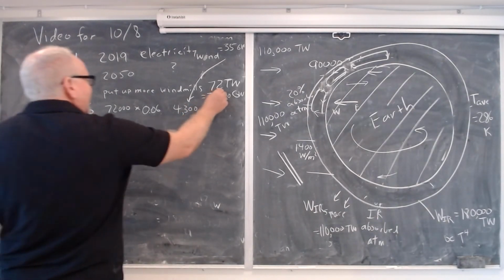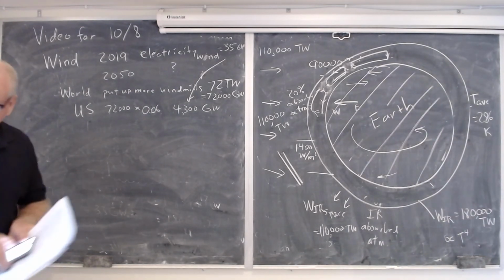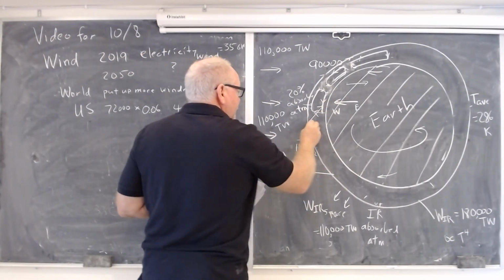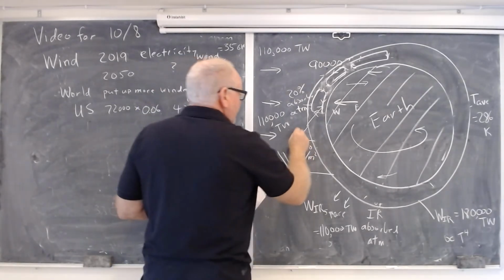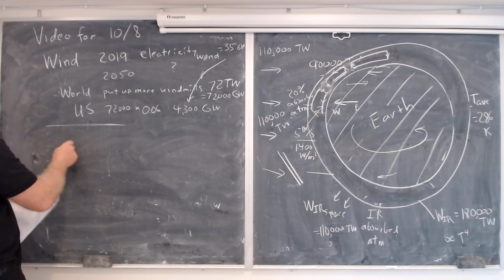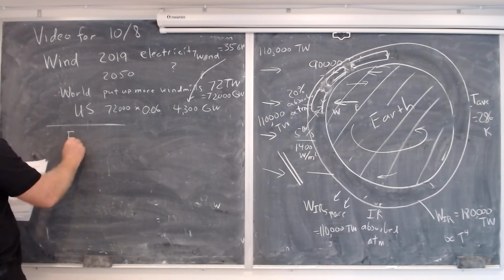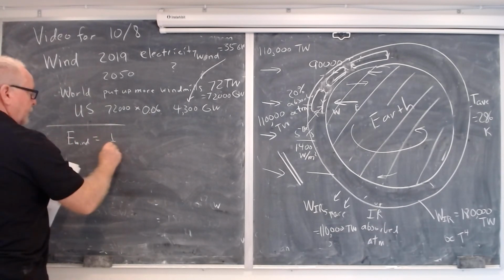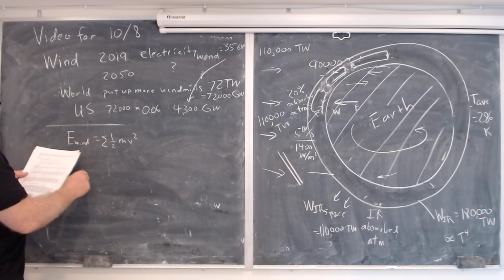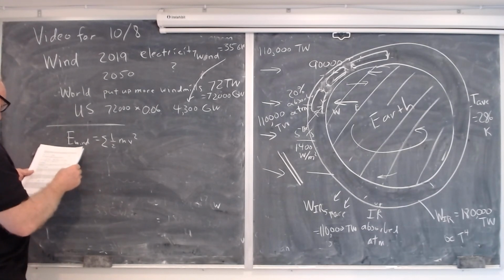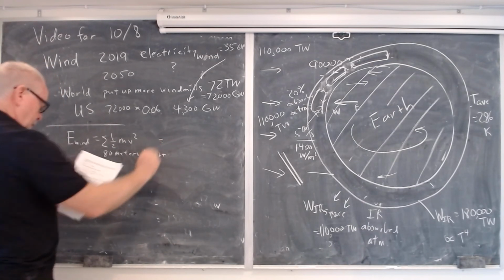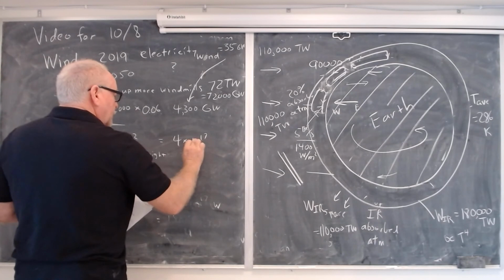One is that this number seems high, and so what I did in the notes was I took an average wind speed of 5 meters per second over land, and this is a different calculation, to take the energy in the wind as 1/2 mv squared, and summing it within 80 meters height, and I came up with 4 times 10 to the 17 joules.